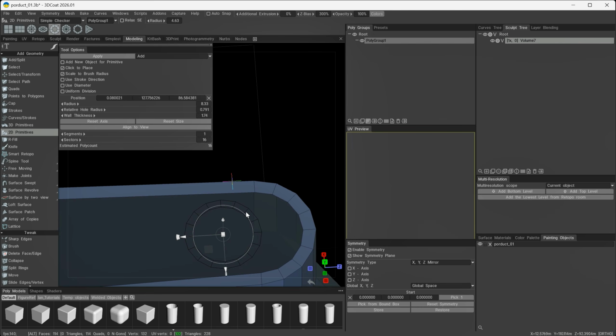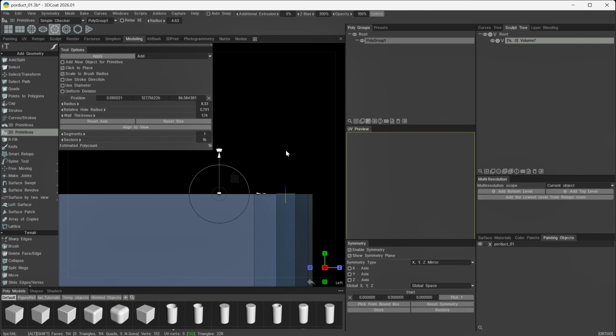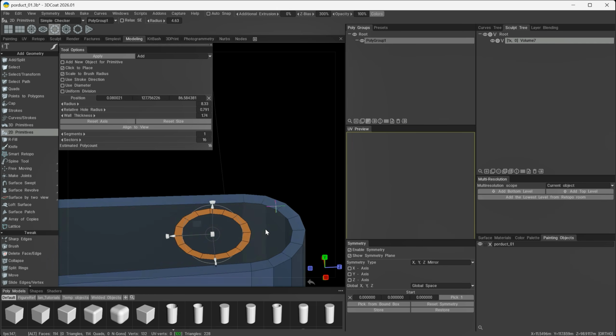Something like that. And again, we've got the issue where the normals are now facing in the wrong direction. So we need to make them face in the positive Y here, upwards. I'll snap to my side view, left click on this little icon here, press spacebar and enter a value of 180 degrees to flip that right the way around like that.